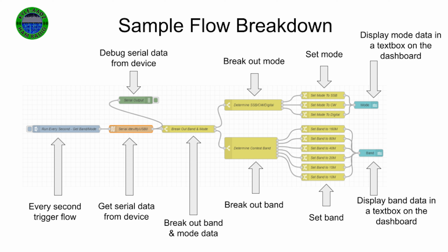The value that I'm probably getting out of my radio is probably two values, the mode and the band. So the mode is probably a text value that says CW, and the band, let's say, says 20 meters. So actually, it's going to come in here, and then it's going to break out that mode, CW text. It's going to say, do I see CW there? And if it does, it's going to bring it up here.